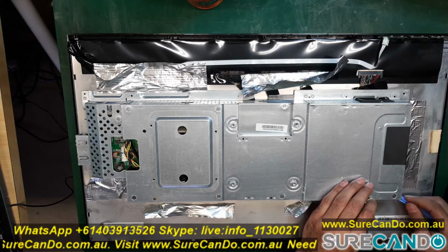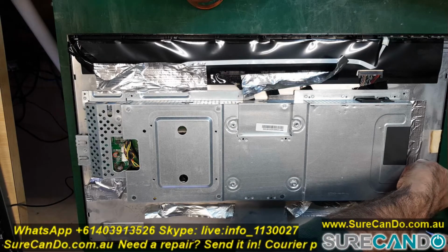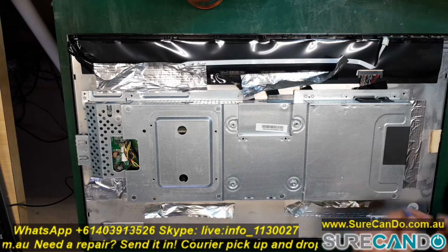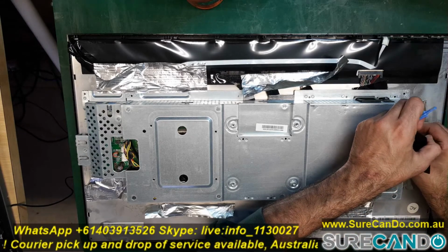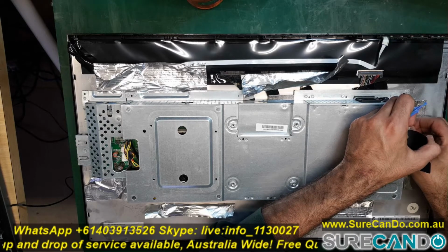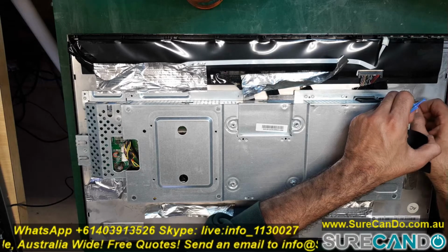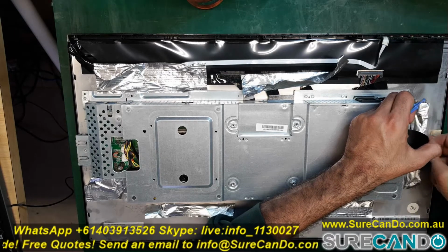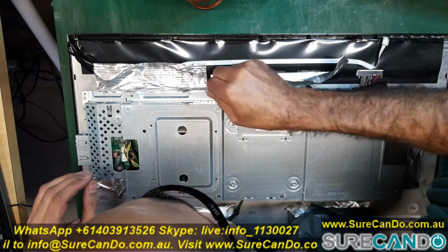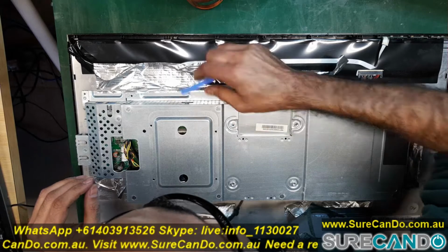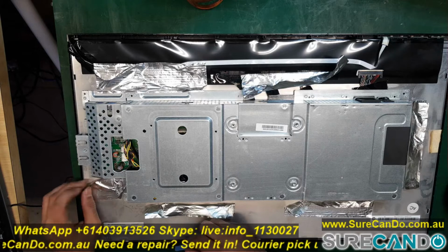So I'm just taking my time, prying all the adhesive all around the edges, and there are actually 4 LCD connectors, and also a backlight cable on the top left, and a controller cable for the buttons that's running along the top line there, right on top of my hand. So it's good to apply a bit of heat to loosen the adhesive and gently remove all of this